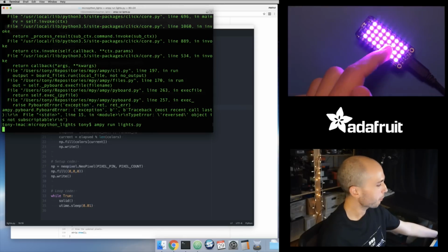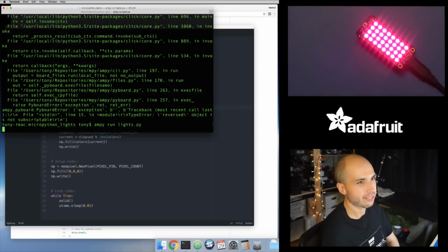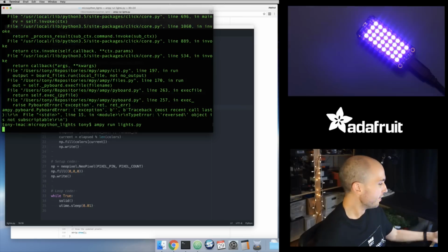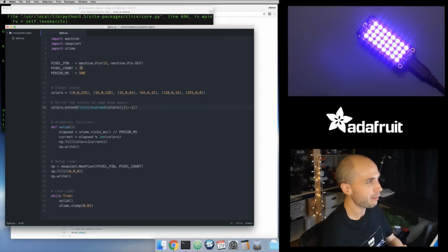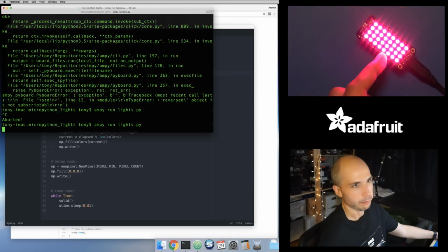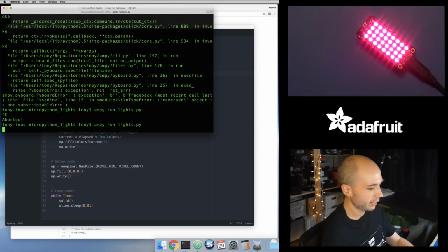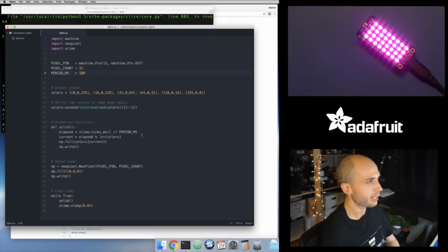You can see it gets up to red and it gets down to blue, but it doesn't stay there twice. It's skipping those end results. And so this is now behaving exactly how the Techno-Tiki project would behave. If I want to change this, I can just change my period milliseconds. This should speed it up. So if I run this, now you'll see it runs a little bit faster. Boom, it's going through the colors, and it's only spending 100 milliseconds at each color here. Okay, so that's the basic animation stuff working here.